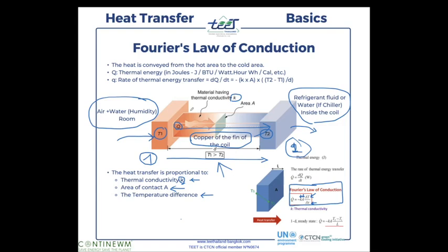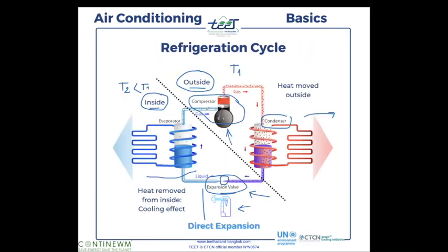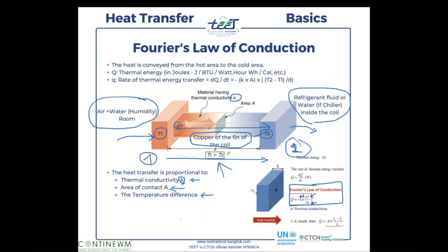On the other side, on the condenser coil, we have the same refrigerant fluid, but remember it's high pressure and high temperature because it's compressed gas, okay? So what happened? We are in exactly the same case. But in this case, here is the compressed gas inside of the condenser, the conduit with the gas here, okay? And outside is the air, okay? But the gas is hotter than the outside.